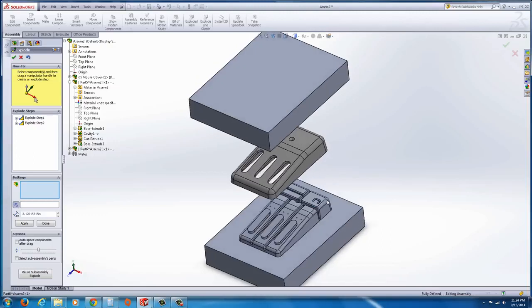Later in this book, the very second last lesson, I believe, we go through how to use configurations when designing a mold. Now, be aware molds are extraordinarily complex. Configurations aren't always the best method. It almost gets a little too confusing from time to time. So you might want to just do what I did here, where we just keep making additional parts. It's easier to understand on the feature tree.